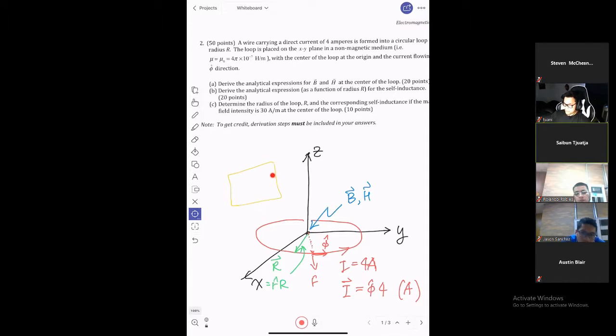Of course, you have to do the dot product. Divided by I1, that gives me the mutual inductance between these two circuits. Does it make sense? The result will be the same. If I know the current over here, I can calculate how much flux is captured by this particular circuit here. The ratio of the flux captured here to the current over here is called the mutual inductance. Any questions?